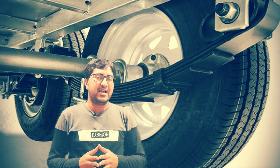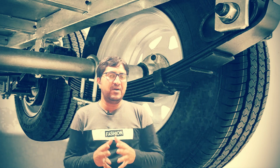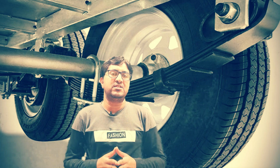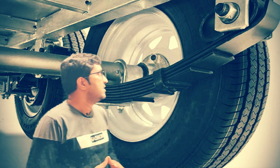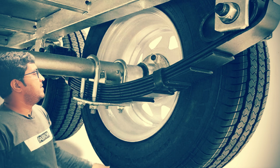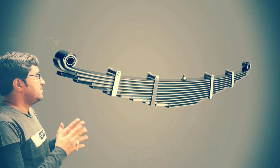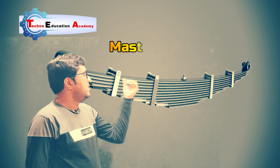But nowadays in a car we are using shock absorbers. In a heavy loaded vehicle, the leaf spring is used in the front suspension as well as the rear suspension. Here you can see a semi-elliptical leaf spring. In a semi-elliptical leaf spring, the largest leaf is called the master leaf.